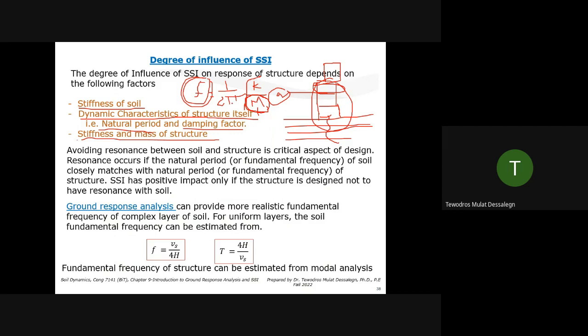If you see it's getting close to the resonance or high acceleration area, you can play with m, the mass, like a water tank, simple example. Or you can play with k. K is what? The stiffness of the structure: beams, columns, slab. You can increase or decrease k, stiffness. If you play with any of them in m over k, you can shift the frequency.